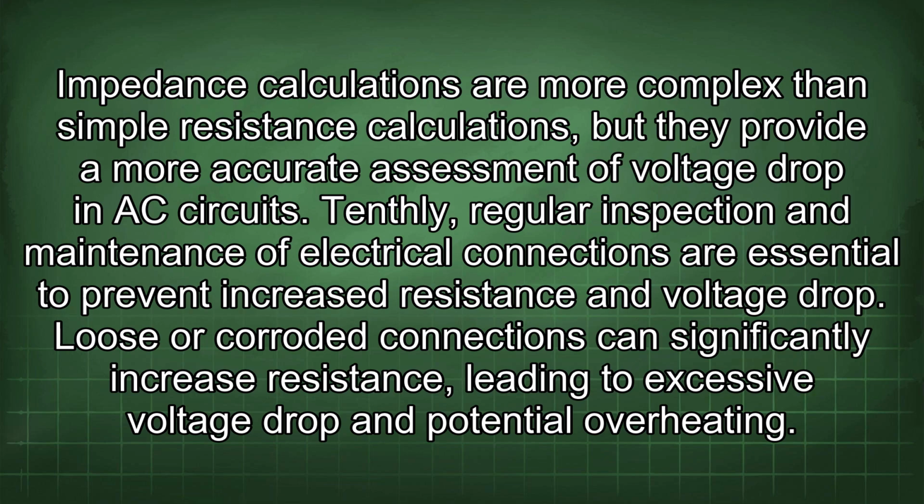Tenthly, regular inspection and maintenance of electrical connections are essential to prevent increased resistance and voltage drop. Loose or corroded connections can significantly increase resistance, leading to excessive voltage drop and potential overheating.